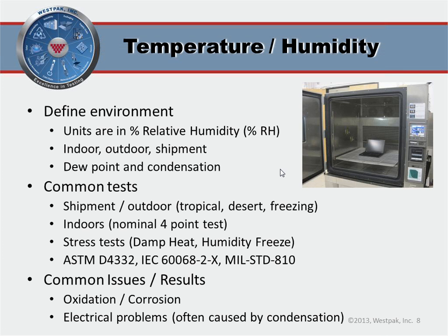And there's also something called humidity freeze testing, where you go from a high heat, high humidity condition and rapidly freeze down, looking at how when water condenses and freezes on a product, if it forces mechanical separation. Think about water freezing in pavement as an example of a real-world application of this. Common issues and results, as you would expect, are corrosion or oxidation of parts, and as I mentioned before, electrical problems caused by condensation. Herb would like to add something.